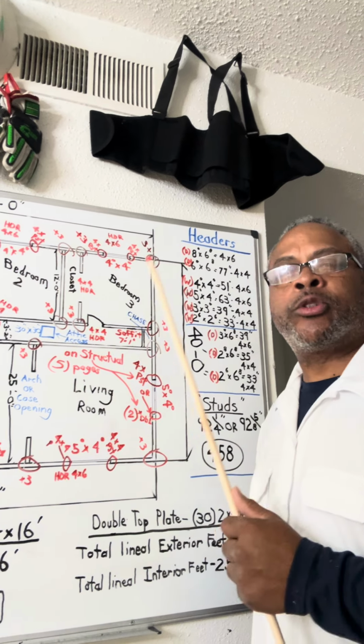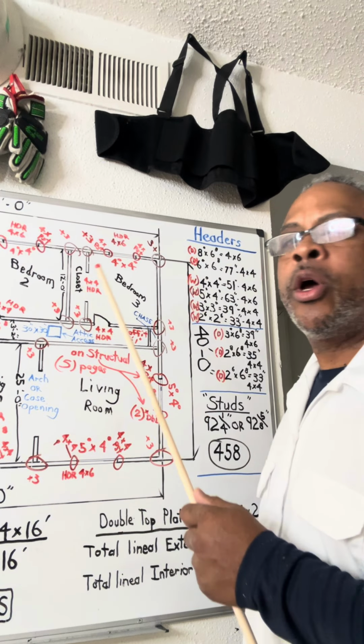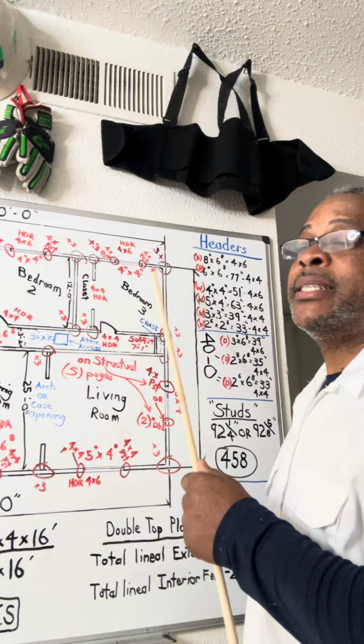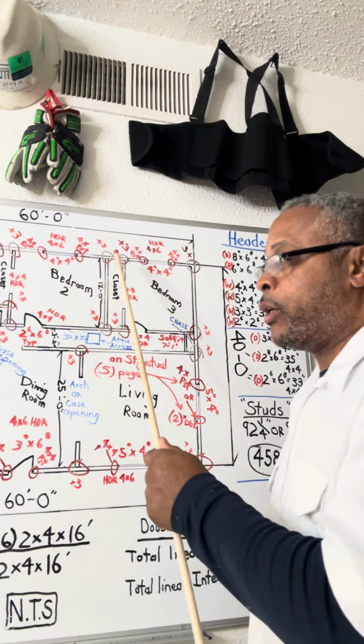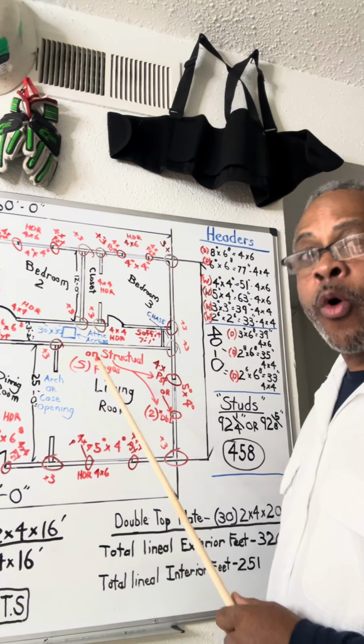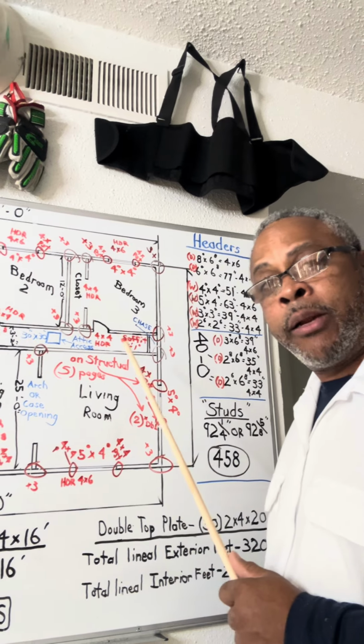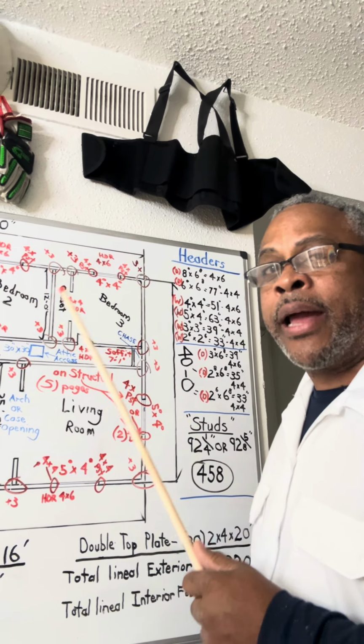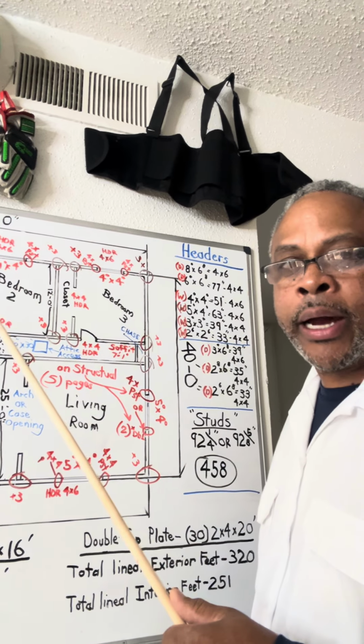The layout guy is responsible for cutting all your bottom cripples, all your top cripples. He lays out all your plate. He lays out every stud, every wall channel; every connecting wall is snapped out by him and plated by him. Headers are cut by him. Doors are 5 inches more on the header stock.